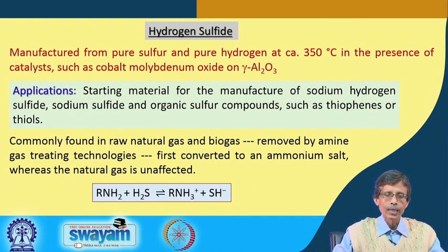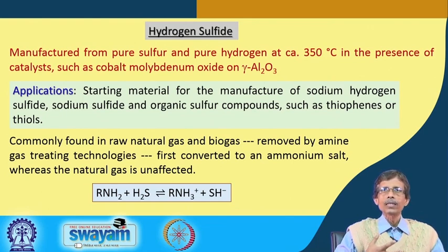When they are together in solution, they are separated as cation and anion, but when you try to isolate it from the salt, like sodium chloride isolation, you get the corresponding ammonium bisulfide salt. So, you can recover ammonium bisulfide salt as a value added product. So, recovery in terms of its corresponding salt is also achievable for the entrapment of hydrogen sulphide in the natural gas.